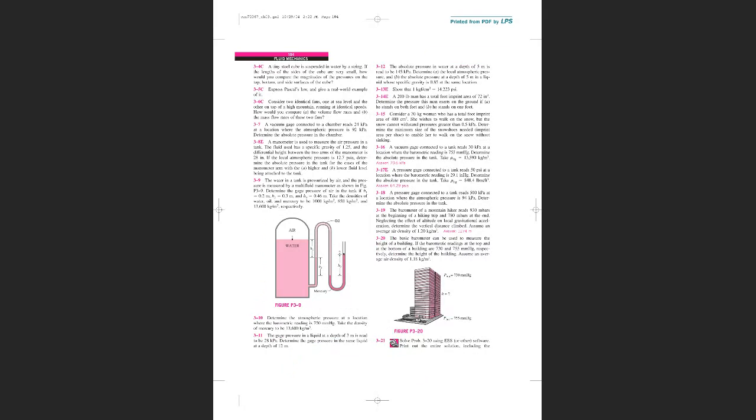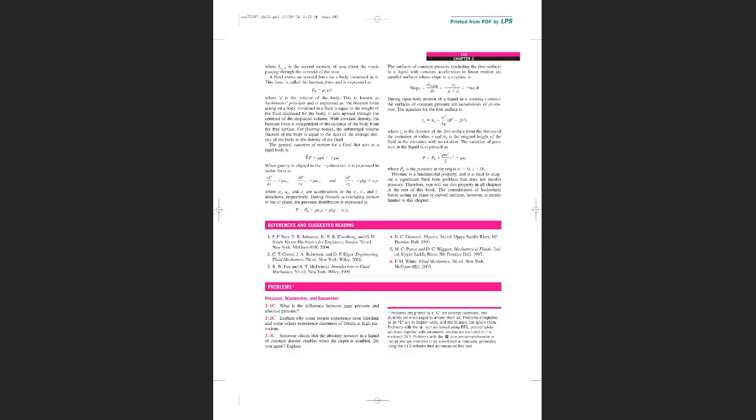Okay, but be very careful here. This is correct if and only if you assume the density is uniform, right guys? And also that G holds its value, because there is modern research which says the gravity G varies with the height and varies with the depth in the water. But if you assume rho G, that is the specific weight, is constant, if you double H you will double P. Right or not, guys?